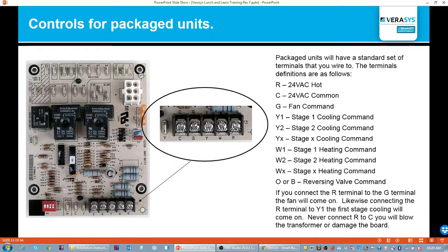What I'm also looking for is, if it's a third-party unit, a conventional thermostat interface. Again, if it's a Simplicity Smart Equipment unit, then I don't need the conventional thermostat interface. You'll recognize this interface by the various terminals for how you connect up a thermostat: an R, a G, a Y1, Y2, a W1, W2. If it's a heat pump, it'll have a reversing valve. So this is a sign that you have a packaged equipment unit when you have something like this. And that's essentially what we support at this point in time.